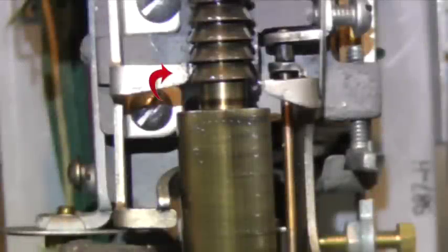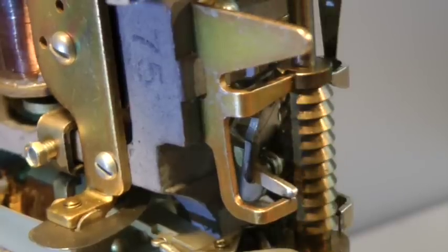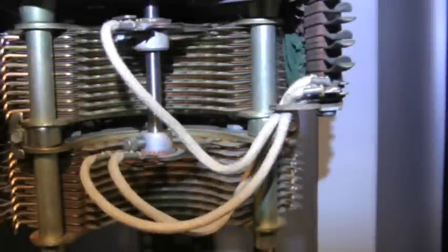The upper leg of the stationary dog is still engaged with the tooth of the vertical ratchet. As such, it provides support for the shaft as it rotates anti-clockwise. When the shaft reaches its normal rotary position, the stationary dog's upper leg rests inside the channel of the vertical ratchet, thus removing all support for the shaft. Without support, the shaft drops down to its normal position by force of gravity. This includes all of its attached apparatus, such as the wipers.